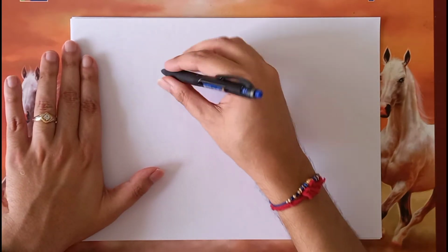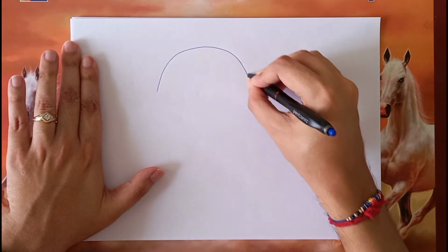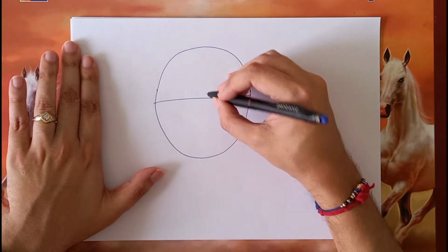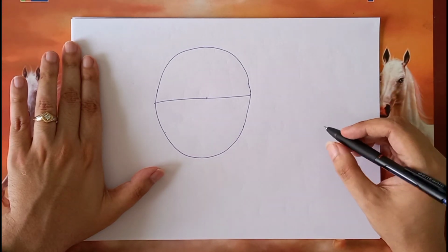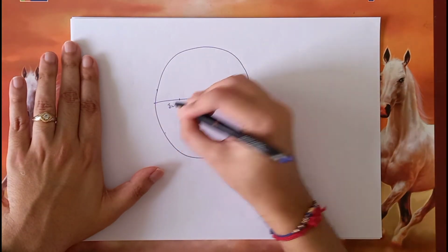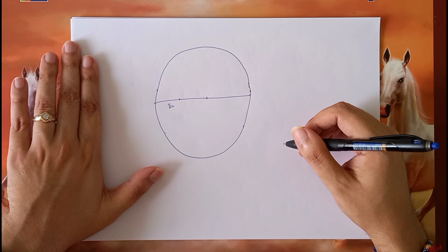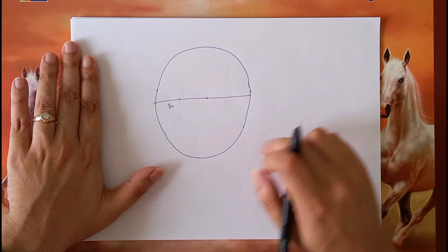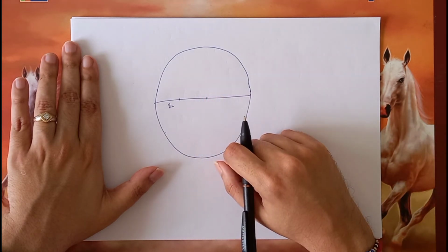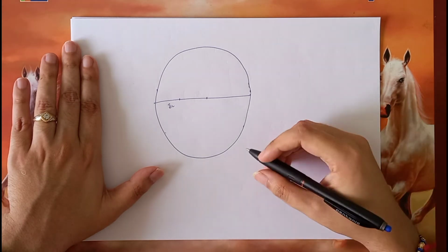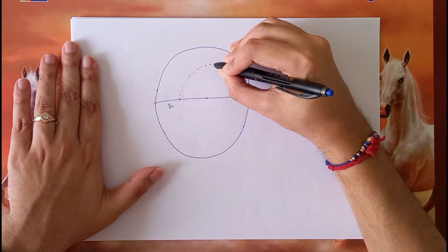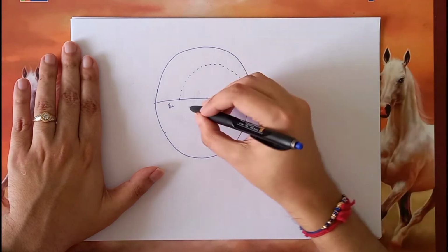So, suppose I have a Smith chart over here. This is the center of the Smith chart. Now let us suppose I have a load impedance over here. This is ZL. So if I want to do the matching of this normalized load impedance small zL to the center point, if I need to find a path by making use of LC networks, what I can do is essentially use the constant resistance circle that this impedance is a part of.